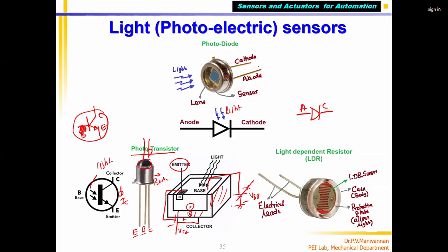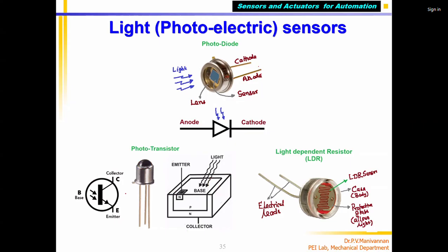But in the case of a phototransistor, you don't need this. Without that, if we shine light on it, the base will start conducting. It conducts automatically. Current will flow, this IC. We'll see how it works. So this is the basic structure of the symbol and how it looks physically. This is the internal architecture, the physical photodiode and the symbolic representation.